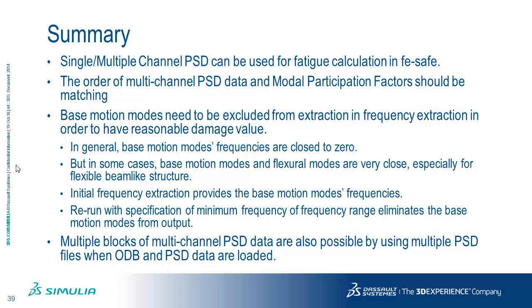So based on whatever we investigated, we can do the single or multiple channel PSD fatigue analysis. And the key message I want to give you is the order of multiple channel PSD and the step definition should be matching. And also the base motion modes, you had better exclude from the analysis in order to get reasonable damage results. Okay?